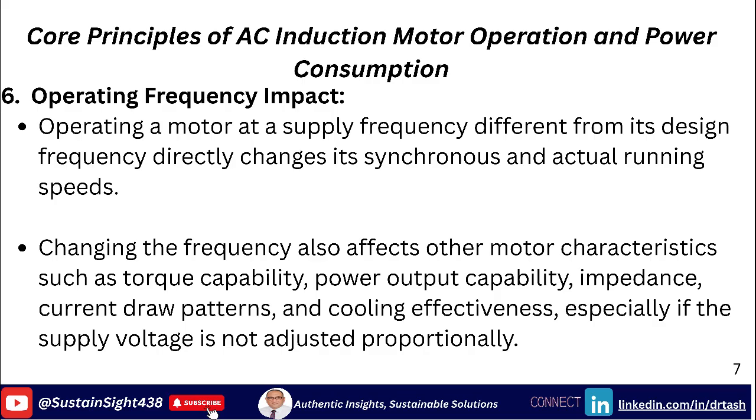This leads us to the principle of operating frequency impact. Running a motor at a frequency different from its design frequency will fundamentally change its speed. But it's not just speed. Altering the frequency, especially if voltage isn't adjusted proportionally, impacts the motor's torque capability, its maximum power output, how it draws current due to changing impedance, and even how effectively its cooling fan works. Motors are optimized for a specific frequency range, and operating outside that range requires careful consideration or specialized control, like a variable frequency drive, VFD.